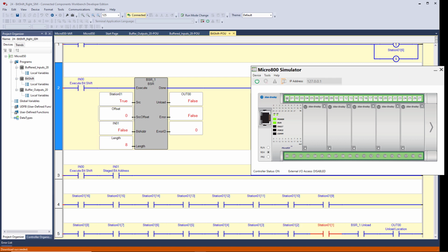And on the next one, we would expect to load input 1 into here. We've been loading zeros in here all this time, every time we toggle this on or off. So just to make that look a little more tidy, I'm going to turn on input 1 so you can see that something comes into 8 when something goes from 1 to the unload. So we'll toggle 0 on and off. And it happens when the execute goes on, not when it goes off.